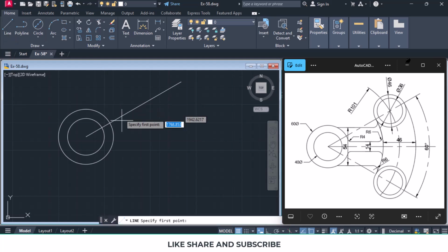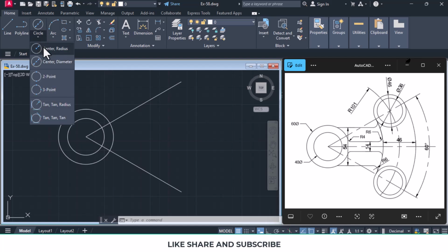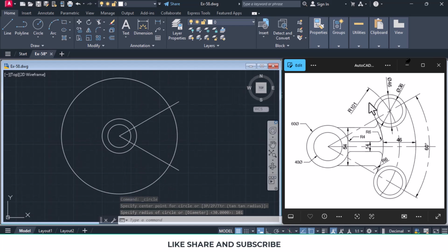Again, we select line command. We snap to the center point of the circle and we give the distance for the line as 120 units and angle is 30 degrees and hit Enter. Again Enter to end the line command. So this total angle is now 60 degrees. Now we'll draw this circle of radius 101. So we select circle, center radius, snap to the center point and give the radius as 101 and hit Enter. So the circle of radius 101 is now ready.